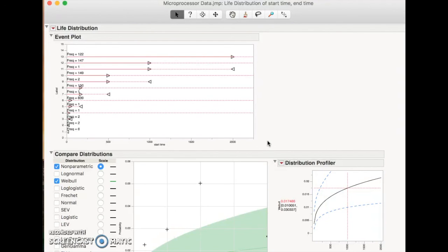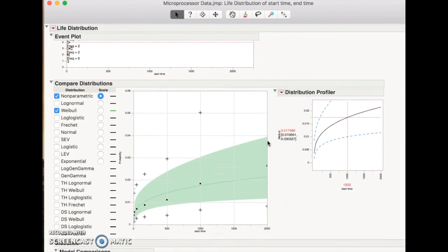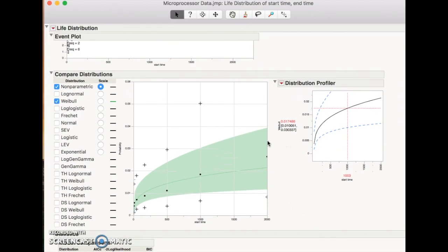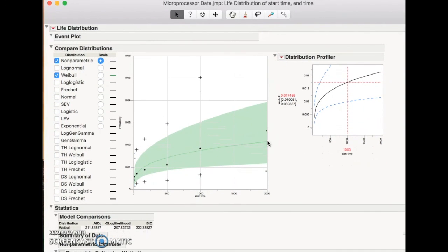On the compare distributions plot, the stars represent the confidence interval. Within the fans produced by the Weibull distribution, we are able to determine the probability of failure with the start time at a known time. This distribution is very useful when predicting warranties, where the hazard function will likely be used.